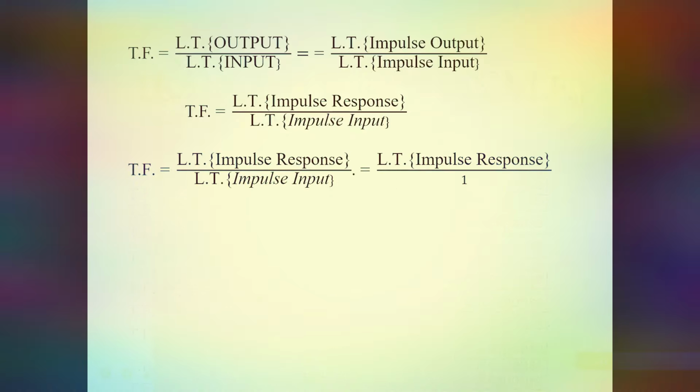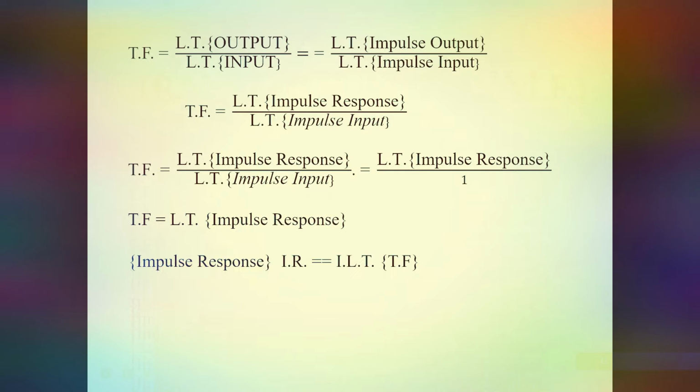The Laplace transform of the impulse input is 1. Therefore, we get the transfer function equals the Laplace transform of the impulse response. From that, we obtain the impulse response: impulse response equals the inverse Laplace transform of the transfer function. Now we move to the questions.